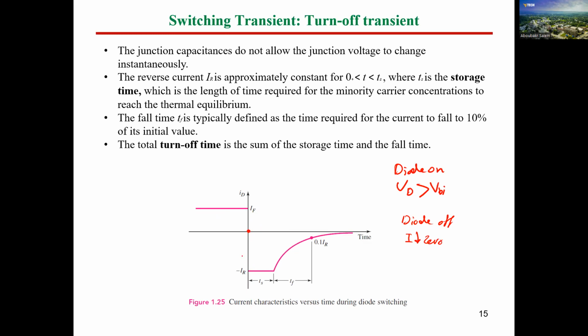What happens is the electrons are already flowing at a very high speed. If you turn off a diode, the electrons are not going to stop immediately. Can you imagine, for instance, if you are driving a car and you would like to stop the car, you cannot stop the car at 0 seconds. In order to stop, the car will be slowing down until reaching 0. This is the same as what's happening in any physical element. Electrons are moving at a very fast speed, so the current is going to move from positive to negative and then decay until reaching zero. This period, guys, is called reverse recovery, and the charge of this period is called the reverse recovery charge. We will see this together in the data sheet.